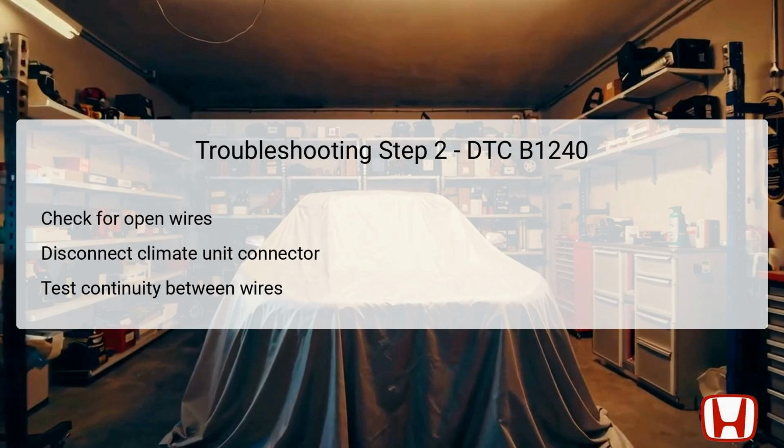For the mode MTR-DF circuit, test point 1 is the climate control unit 32P connector number 5, GRN, and test point 2 is the mode control motor 7P connector number 6, GRN. Additionally, evaluate the vent circuit with the corresponding test points.